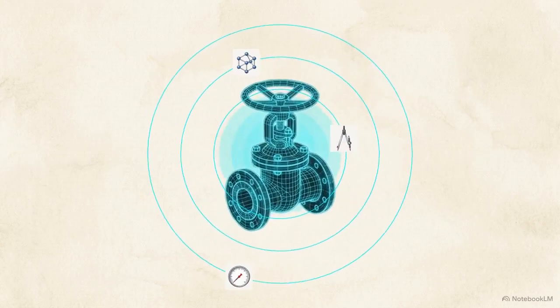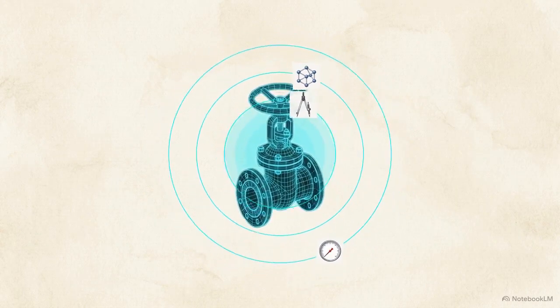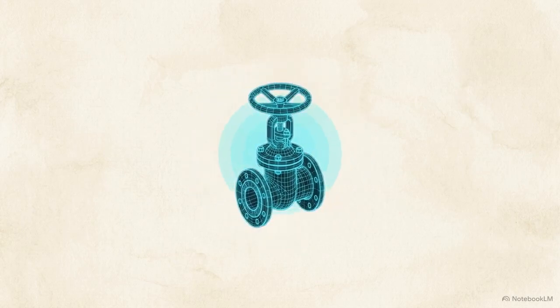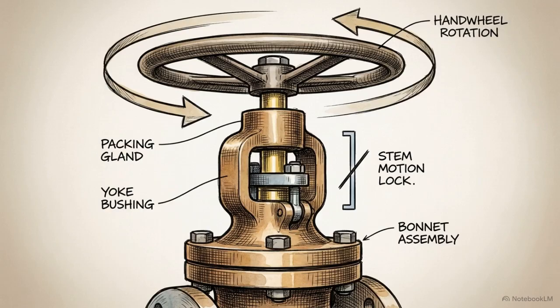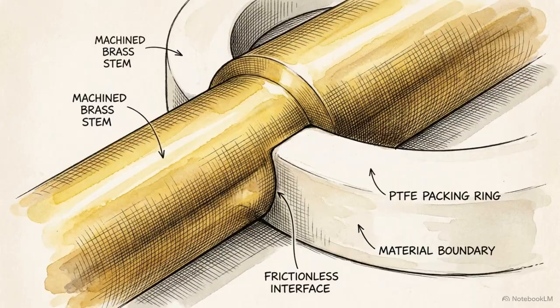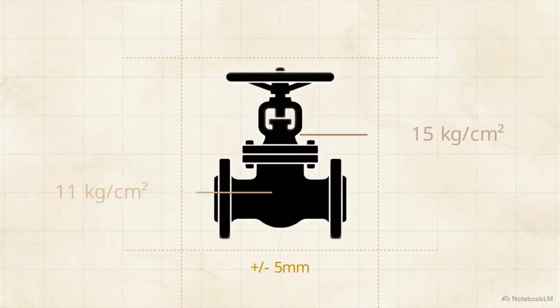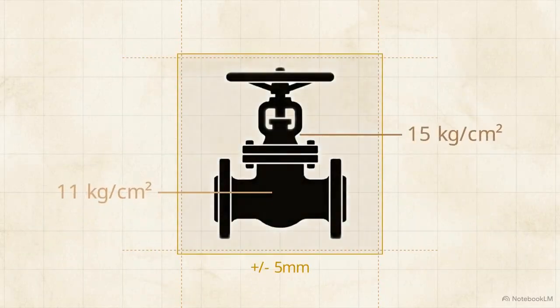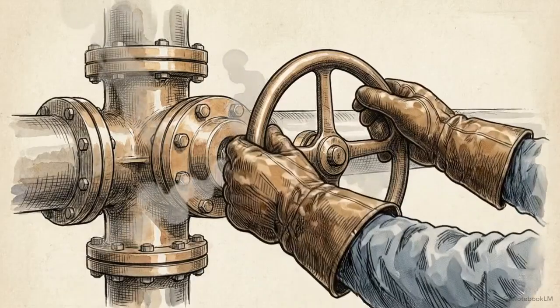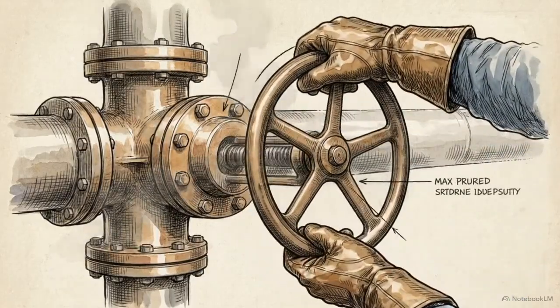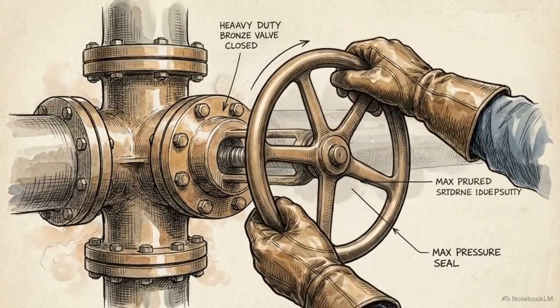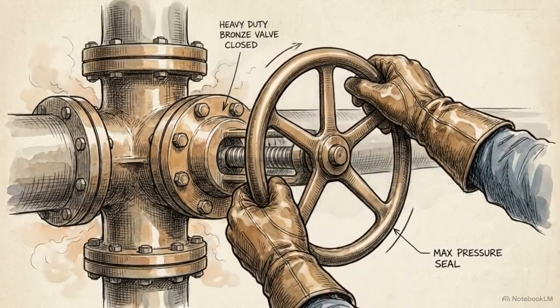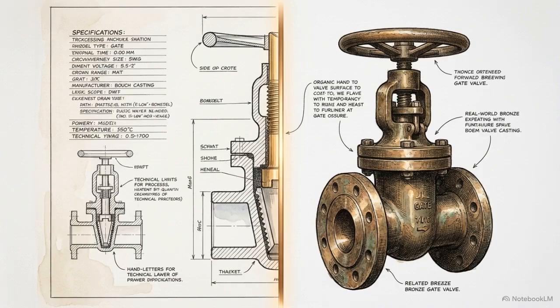Decoding a technical document involves tying these three distinct domains back together. The schematic dictates the spatial kinematics of the non-rising stem. The parts list maps the chemical and frictional survival provided by the brass and PTFE, and the data tables guarantee the modularity and safety margins of the testing differential. Those theoretical numbers finally manifest as a physical, robust industrial component, installed on the line and actively fighting against immense fluid pressure. The specification sheet maps the exact mechanical reality of industrial flow control.